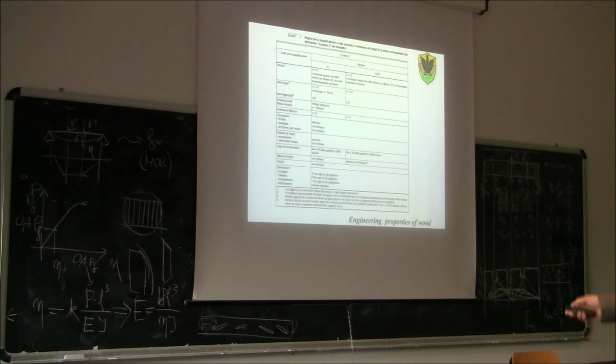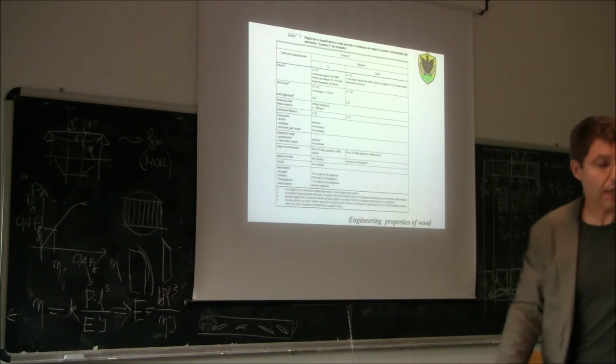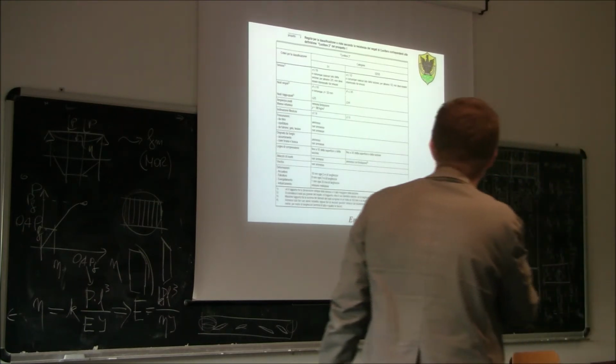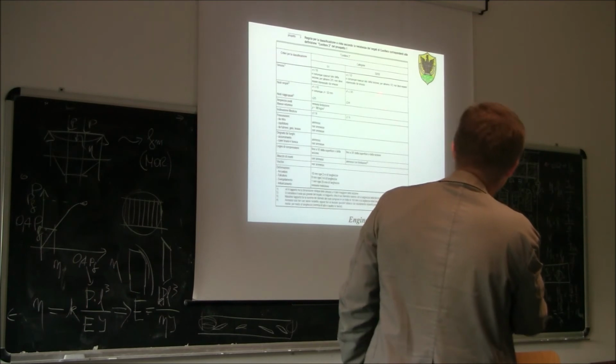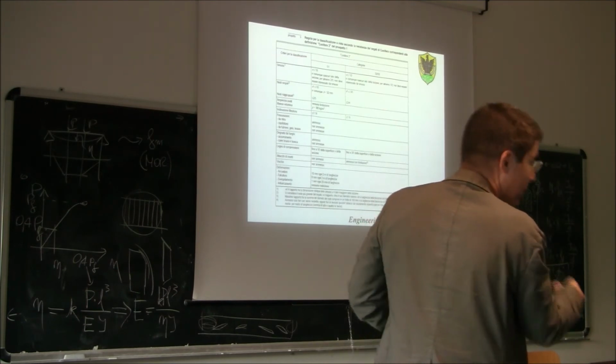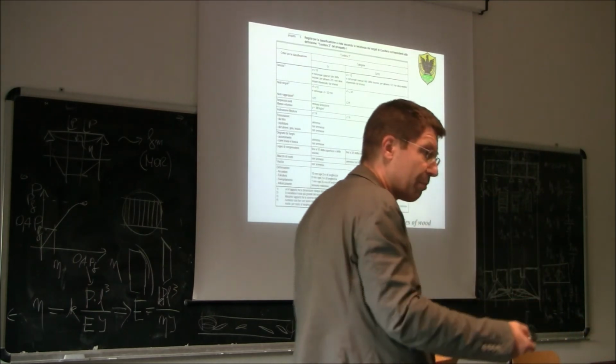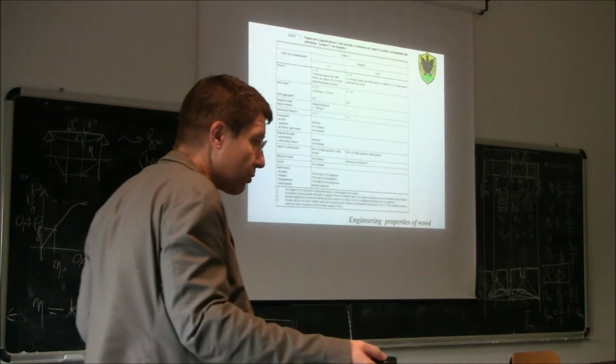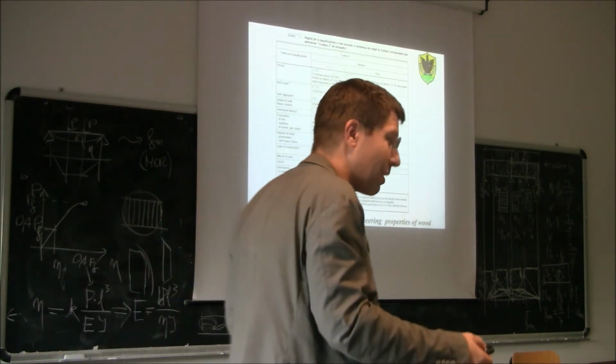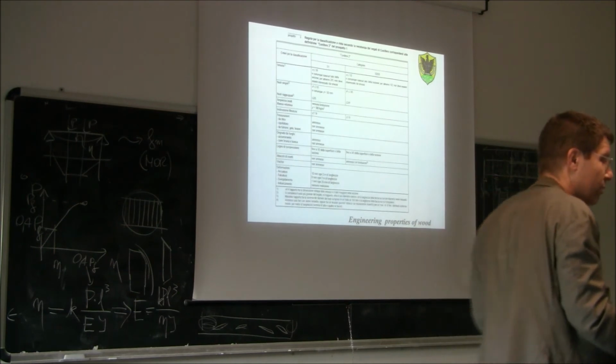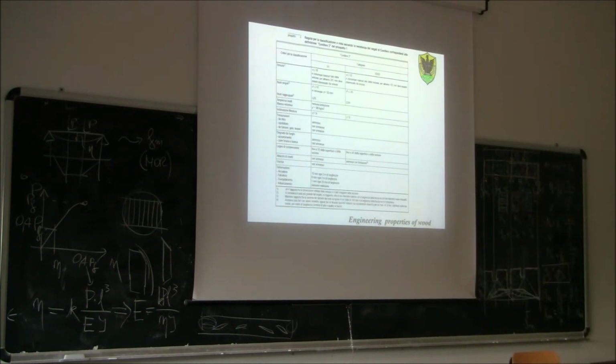So you go to measure, you use this classification here, and if you find that the wood is actually S2, S3, or even rejected, in more than one piece, then the best way, if you want to be 100% sure, is again to call a wood scientist, a wood technologist, who will confirm what you have done so far. And then you start discussing with the enterprise.